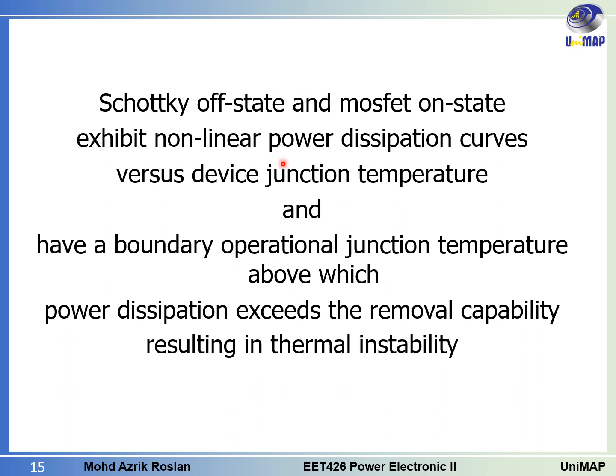So you have to know that the Schottky off-state and MOSFET on-state exhibit a non-linear power dissipation curve versus the device junction temperature. We are specifically focusing on the Schottky off-state and MOSFET on-state.